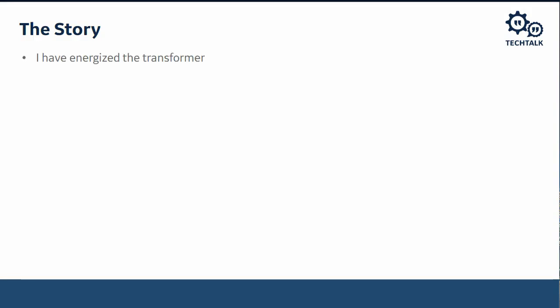Now, but as soon as they picked up load, they got a transformer differential. Now, a lot of times you might operate on a transformer energization. So there's a way to restrain the transformer differential for the inrush associated with a transformer energization event, and that's called harmonic restraint. And usually it's second harmonic restraint.